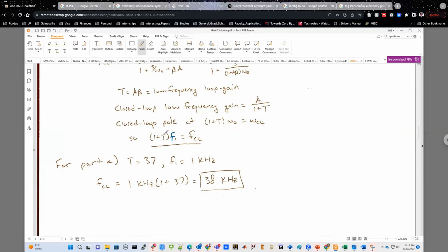After the frequency at which you encounter the bandwidth, it will follow a minus 20 dB per decade slope for a first order response. If it is a second order amplifier, that would be minus 40 dB per decade. We will come to those things later on, but not right now. Right now, let's assume that this is minus 20 dB per decade.